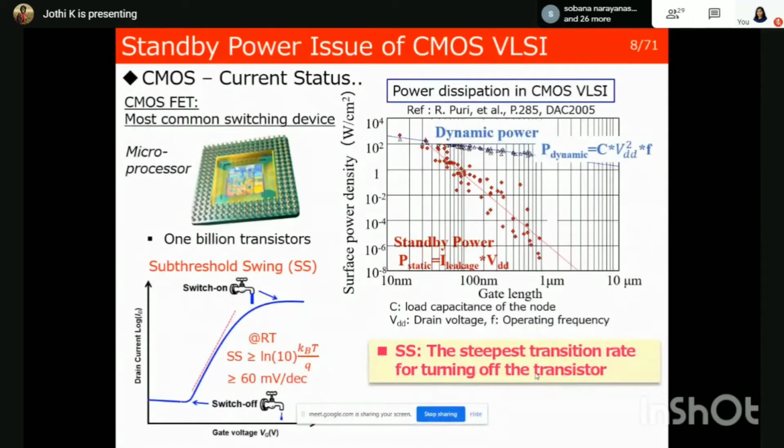So the tap leakage is, let's say, 60. If you reduce this value to any lower value, then you can completely shut down your tap, which in turn shuts down your off-state current, which in turn reduces your standby power. That's the entire deep root of the problem. So our idea is to address this leakage.